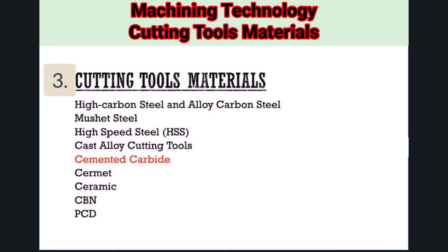Initially, cemented carbide was brazed to tool bodies. Then came the time for indexable inserts, which are the focus of the current course. As the name implies, cemented carbide is a tool material made up of hard carbide particles cemented together by a binder. In the case of cemented carbide indexable inserts, a slurry of cemented carbide is pressed in a die. However, the pressed insert is a soft and porous material. Therefore, pressed indexable inserts are sintered inside an oven.